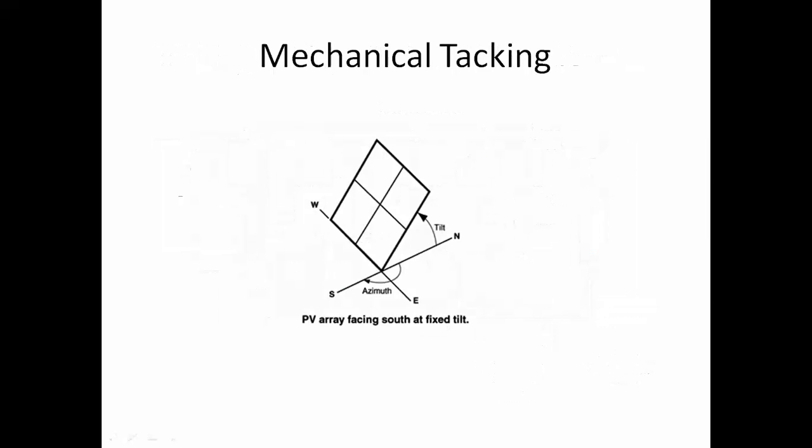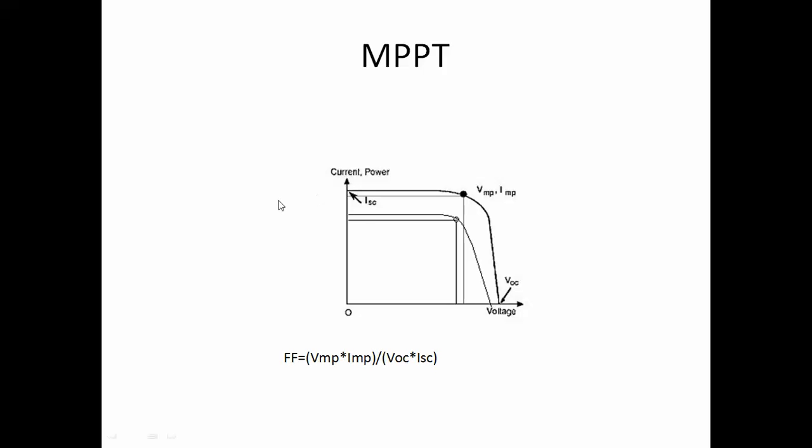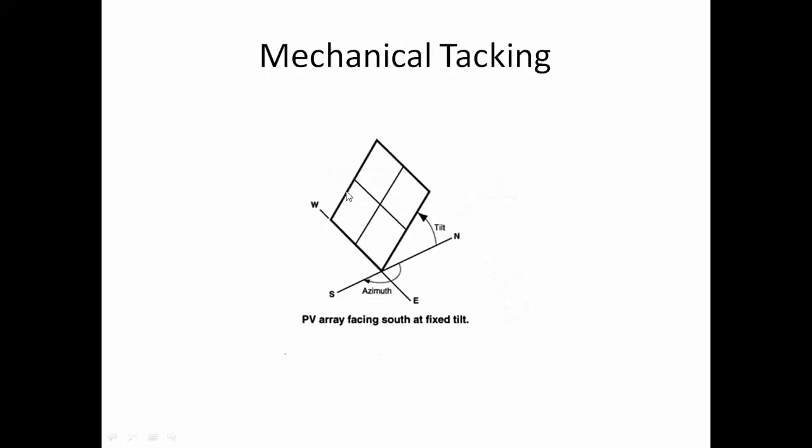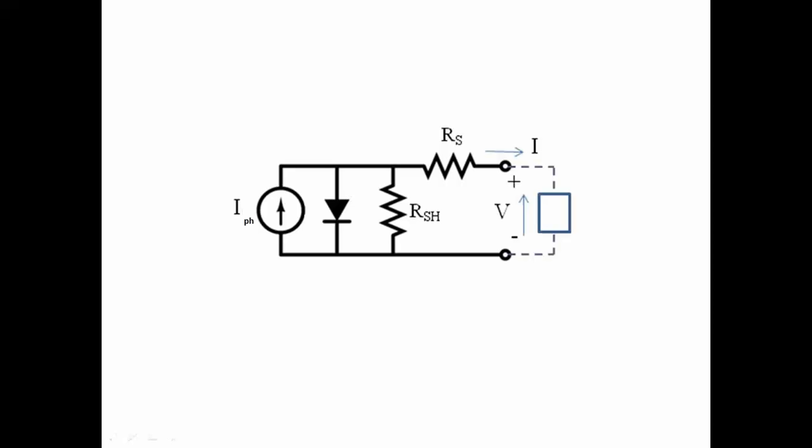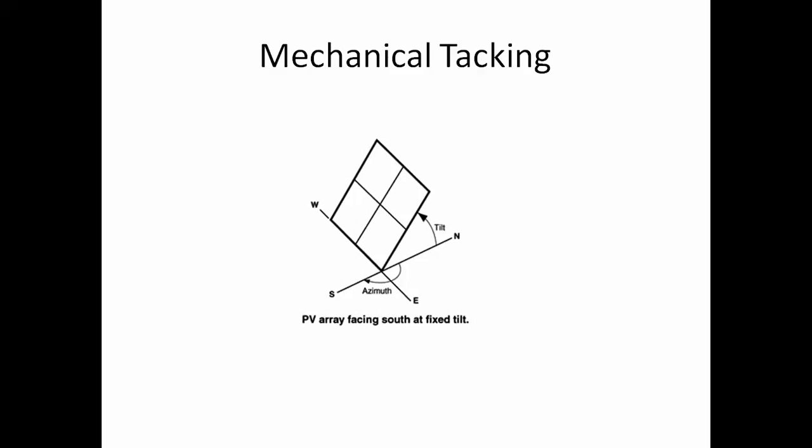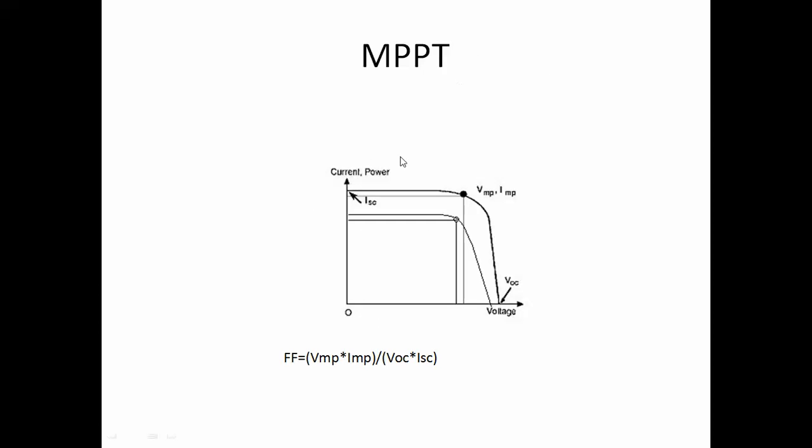Okay, and here this is the open circuit voltage and short circuit current. That is by open circuiting the load terminals. If you remove this load, the voltage available at this end is the open circuit voltage, and by short circuiting these terminals with a wire, we will get a short circuit current ISC. So that is these two things.